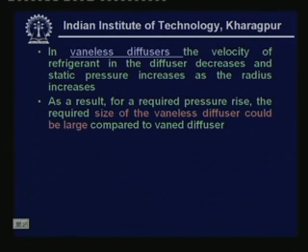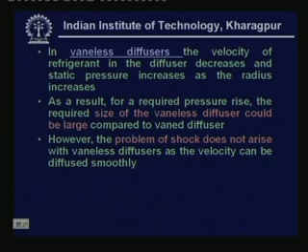So, that is what is mentioned. As a result, for a required pressure rise, the required size of the vaneless diffuser could be large compared to a vaned diffuser. However, the problem of shock does not arise with vaneless diffusers, as the velocity can be diffused smoothly. So, this is an advantage of vaneless diffusers. You do not come across the problem of shock.